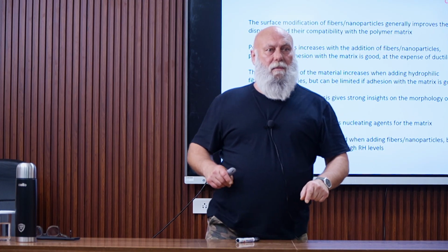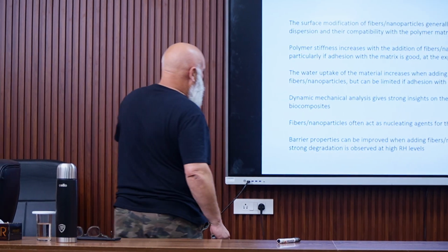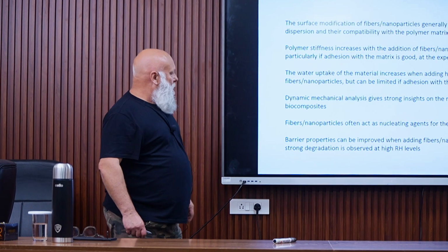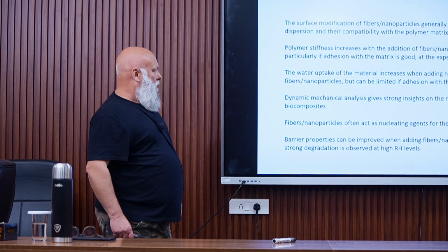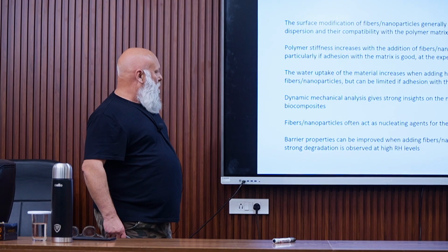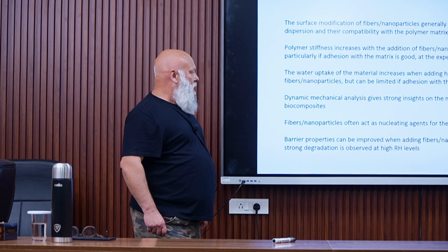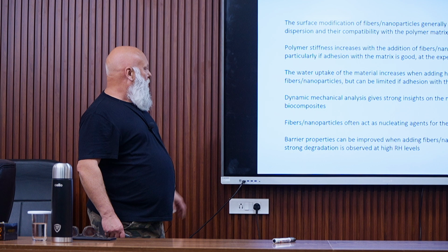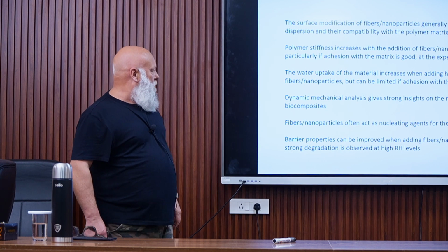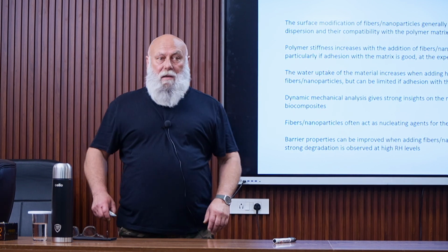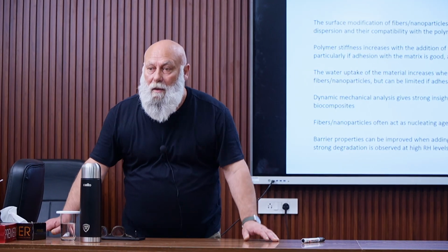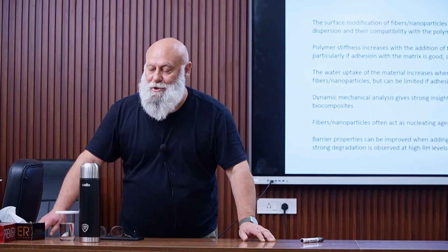Fibers and nanoparticles often act as nucleating agents for the matrix, and barrier properties can be improved when adding fibers or nanoparticles, but strong degradation is observed at high relative humidity levels. Thank you. If you have any questions.